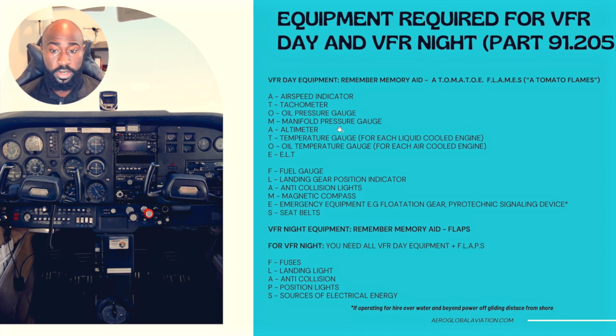So if you're flying VFR day, for example, and equipment from VFR night is not working, you really don't need that to work during the day, so you can still go fly VFR day. Obviously, you want to use some caution, but that's the general idea. But for VFR night, you need both VFR day and VFR night equipment.